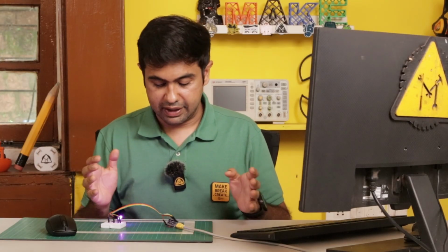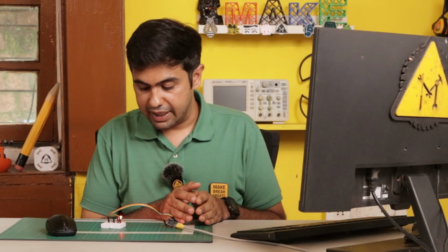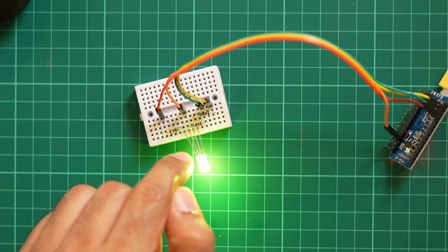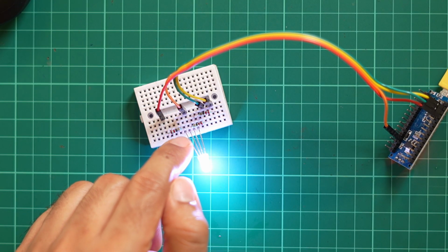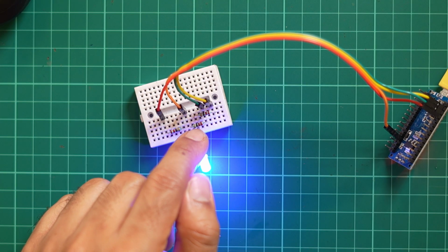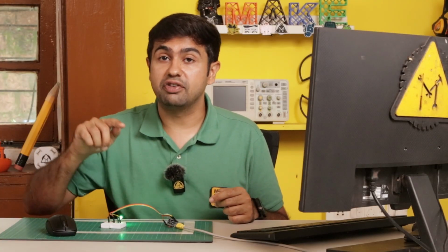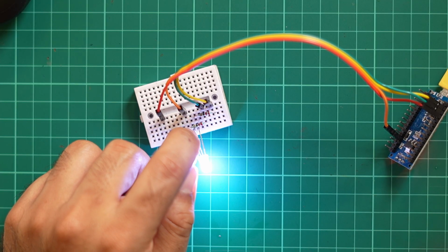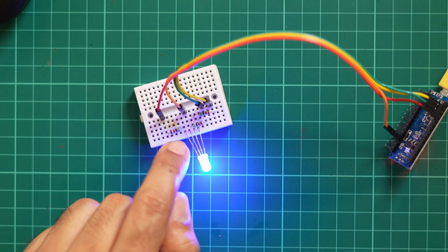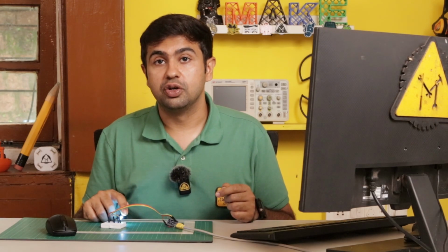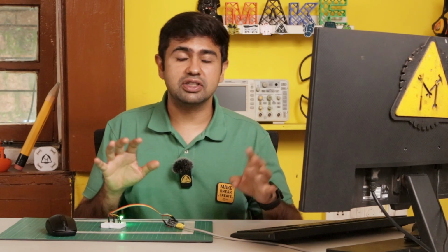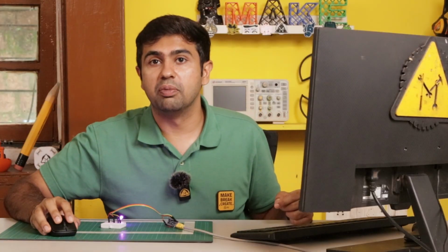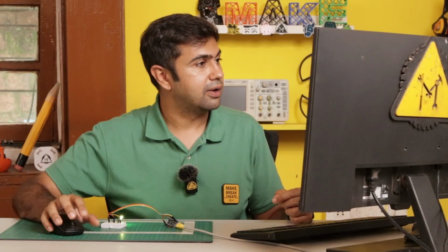What do I mean by that? Now, think of it like this. If I were giving it voltage on blue and ground was actually the common cathode, then we would automatically make sense. However, because we have a common anode, we have to invert everything. And the voltage that's being given from the anode is always at 5 volts. So it has to be the opposite of the voltages to be able to counteract for it. If you don't understand it too much, don't worry about it. We can talk about it later as we get into this program. Once you start doing it, you'll get the gist of it.